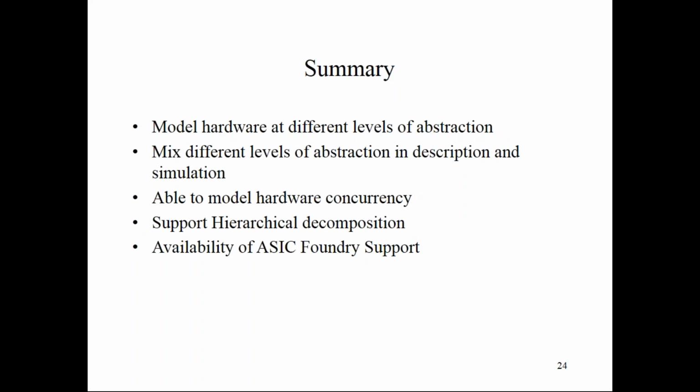For fabrication we are generating a netlist. It's a purely technology independent netlist after synthesizing. Then we are mapping that netlist to the technology.